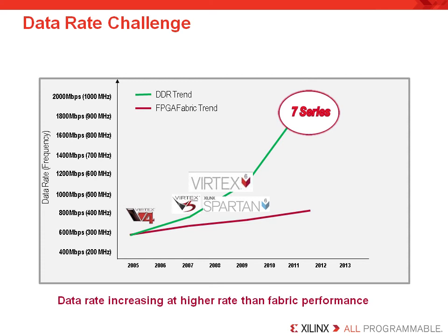The rate of increase of memory bandwidth per pin has far outpaced the overall increase in performance of the FPGA fabric. Conventional methods of using FPGA fabric to implement a high-speed memory controller as soft IP is simply not sufficient to meet the speeds of the newest memories.